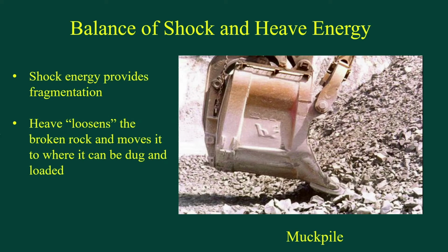So when we look at the energy that our explosive provides us with, it needs to be able to give both shock, which is the energy that gives us fragmentation, and as comminutors that's what we are most interested in, but it also has to provide what we call heave energy, and heave loosens the broken rock and moves it to where it can be dug and loaded. And here we can see what is called the muck pile, which is our pile of broken rock after the explosion, and a ground engaging tool, in this case a bucket, in the process of digging it up.